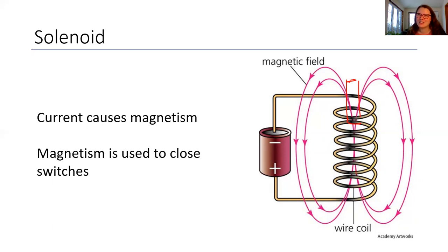I've looked a little bit, I've found a few of them in heat pumps, and it's always used to switch something on and off. When the current hits a certain value, that solenoid is drawn in far enough, a switch is triggered and an effect occurs. In vehicles, one of the places it's used is when you turn your starter switch, so you turn your key over, there's a solenoid that engages and that sends current to your